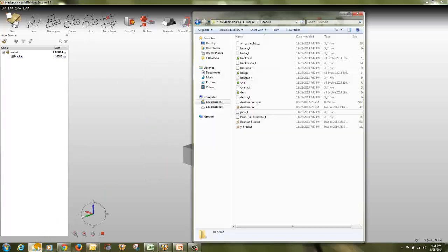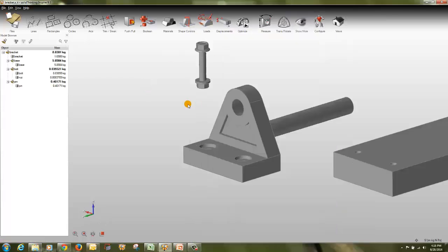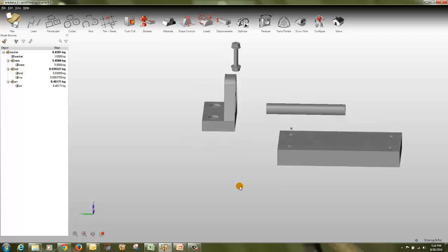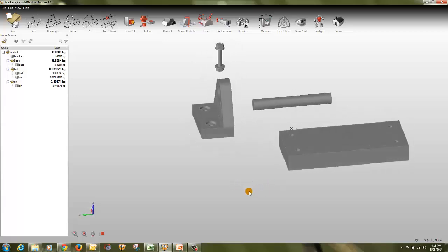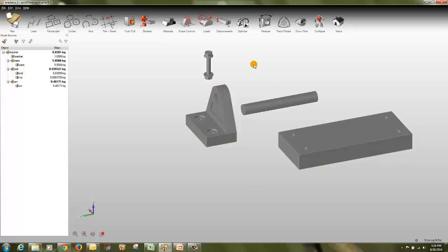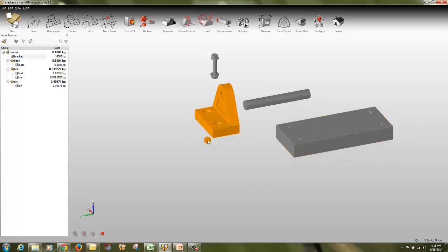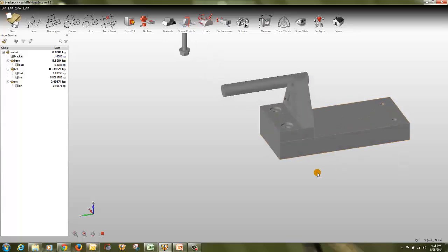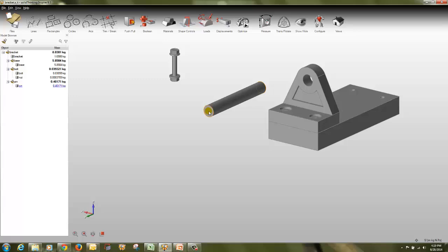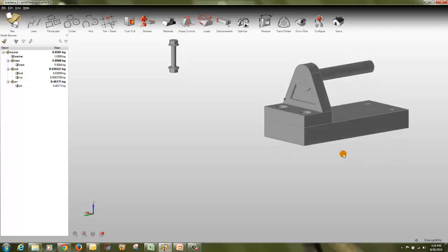And also we will import some more files, like plate, bolt and pin. So these three files we will just copy and paste. You can see these are the files I have imported. Now I will organize this model and make it a bracket. With the snapping tool, you can move this to the end, and scroll it down, and here also to the end. So you can see like this, it has been fixed. Similarly, this from center to this center. So this is done.